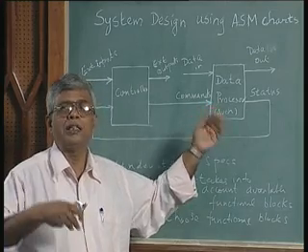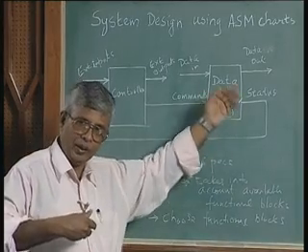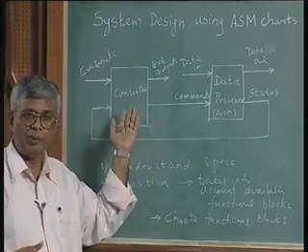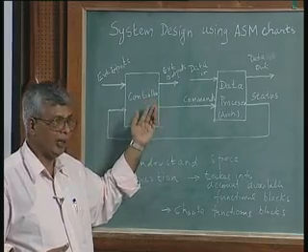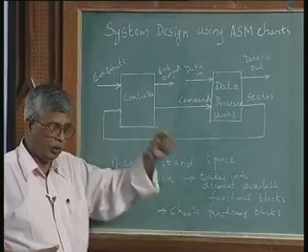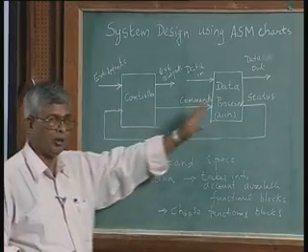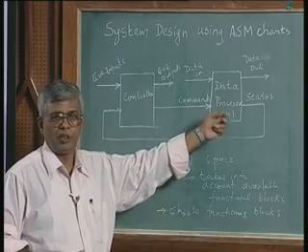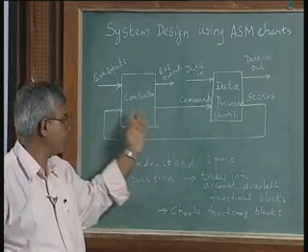So I would not like to do 16 times something. When you put the 16 times in the controller, my state graph is going to become extremely big. 8-bit multiplier, 16-bit multiplier. For each multiply I put a state, multiply, add, shift, each is a state. The ASM chart will be so big with so many states. Instead I can put a counter here, activate the counter, and increment the counter by 1 every time I do a shift. When the counter reaches a particular value, I compare the value and then give the complete signal. So the number of states required for the controller will be small.